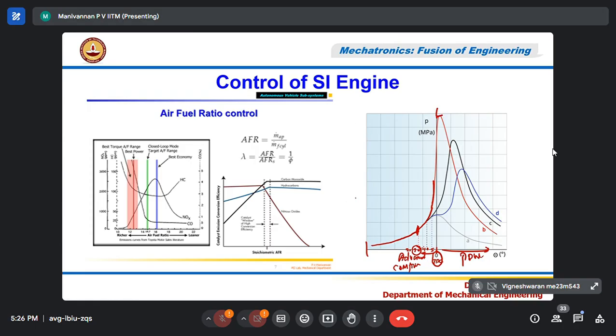The y-axis is the pressure inside the combustion chamber in bar. Correct? For a small engine, say a 100cc engine, maybe some 50 bar pressure. They call it peak pressure. Okay. Now, if I give the spark at 20 degree, the fuel burns for the entire duration, for that 20 degree duration. The piston is moving up, compressing. The fuel is burning, as the spark is already given. By the time the piston reaches TDC, almost 50% of the fuel has burned, and you see the peak pressure being achieved.